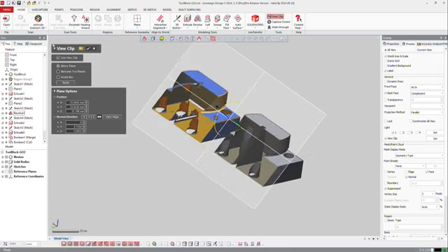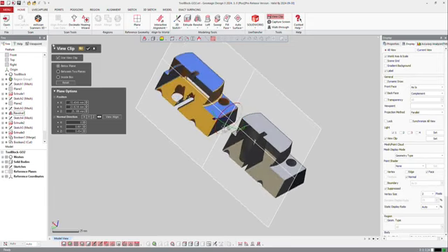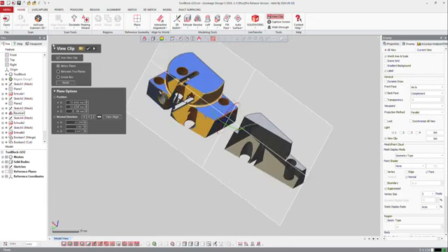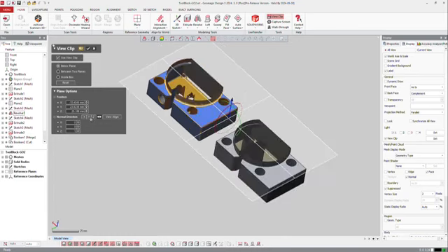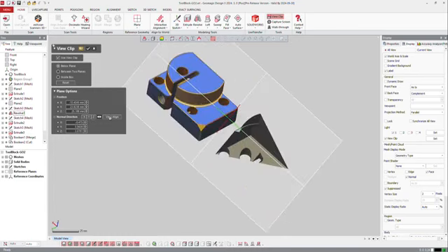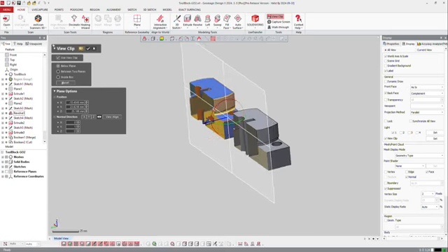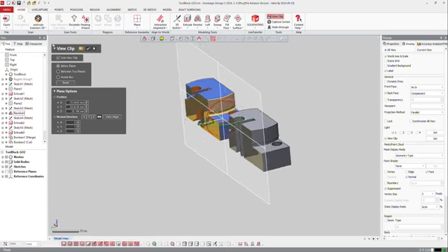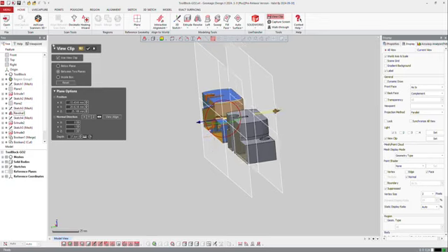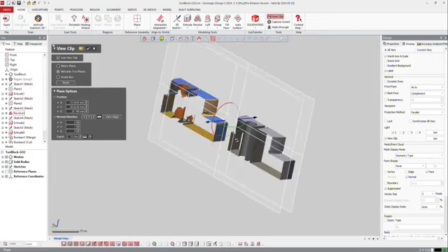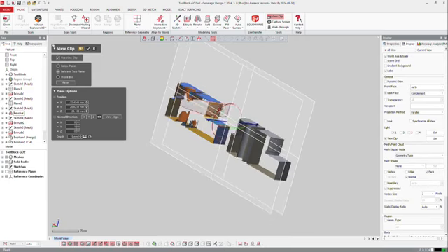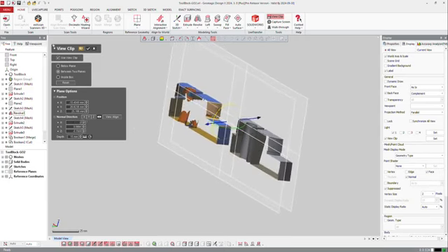You can still turn it in any direction you would like to have, or you can constrain it in plane option and tell the software you want to have a plane in Z direction or Y direction or in the view alignment. So if I put to Z, I got my plane, or if I would put it on Y, and ask the software not to make it only one plane, but two planes, between two planes. It creates a second plane which is parallel to the first one, and then you can make this type of view clip. Of course, if you turn it, everything is synchronized like that.